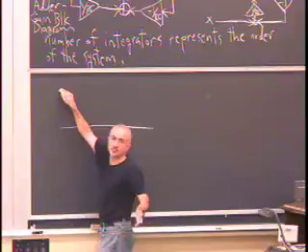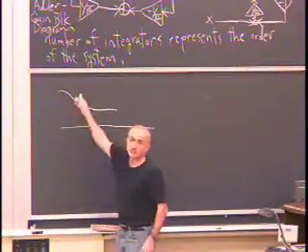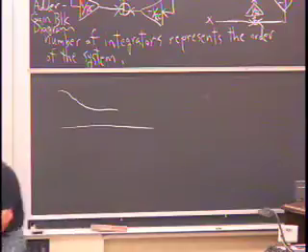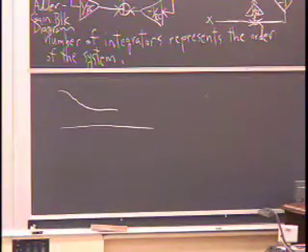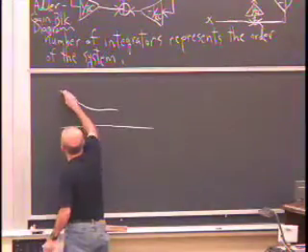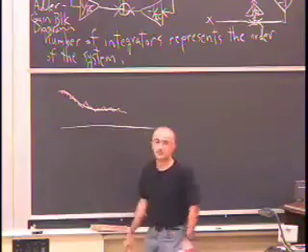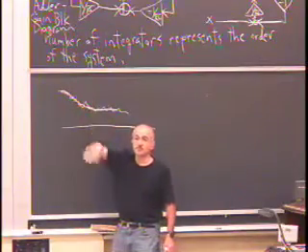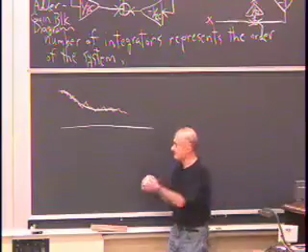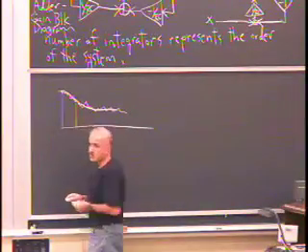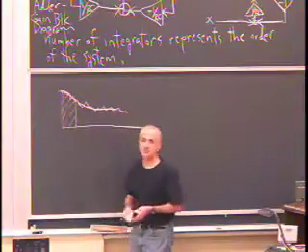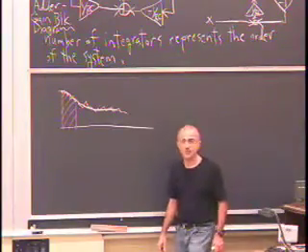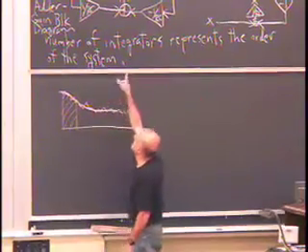So if all my signals had been smooth, no problem. Differentiation and integration theoretically should be okay. But in the real world, you have all kinds of noise. So instead of a nice-looking signal like this, you're going to have a noisy one. Notice how unstable differentiation will be. Going from point to point, it flips wildly. And that's not what you want. Whereas if I integrate the same red signal over some interval, the fluctuations in that integral will kind of average out. So I have a much more stable, numerically stable calculation. So that's why we implement systems using integrators.